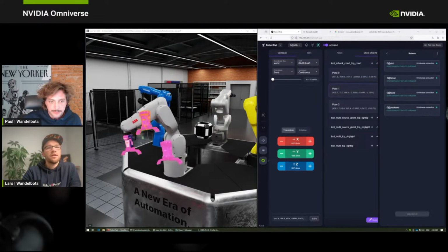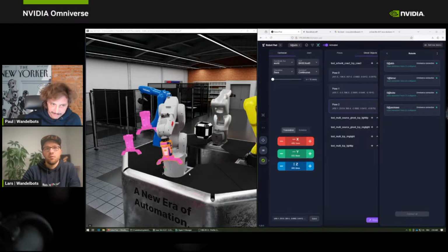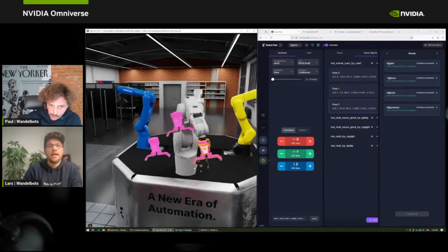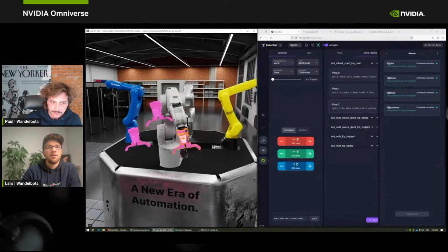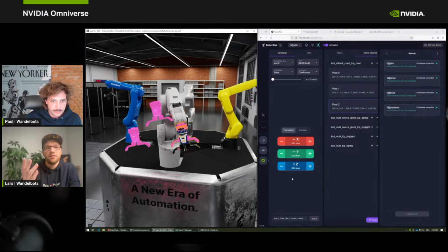And the good point is, we only rely on naming conventions. So if you name your tool, which is attached to the robot, it automatically detects it. You can see also four more objects. And we auto-generate them. So there's no preparation from your side, only the naming needs to be put in and the tool needs to have a TCP. And then you can drag it around and also see that it's outside of the workspace and it sends you the signal that it's not reachable.